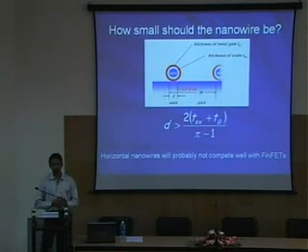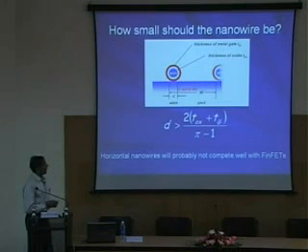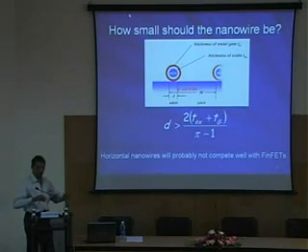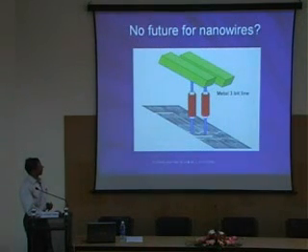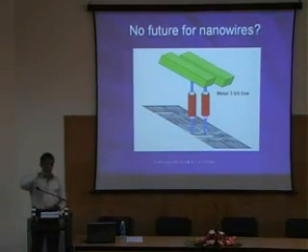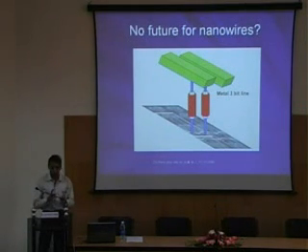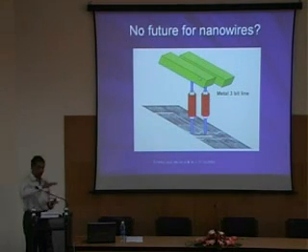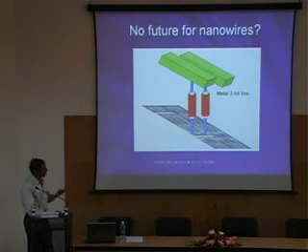So there is a problem in using horizontally laid nanowires if I had to build efficient, highly packed integrated circuits. In order to overcome this problem, what we need to do is build these nanowires vertically. Don't lay them horizontally on top of the silicon surface. And you can also use these vertical transistors not only to pack these transistors very close to each other, you can also use them as pass transistors between different layers of metals on your integrated circuit. So therefore now there is a lot of interest in making vertical nanowire transistors rather than horizontal nanowire transistors.